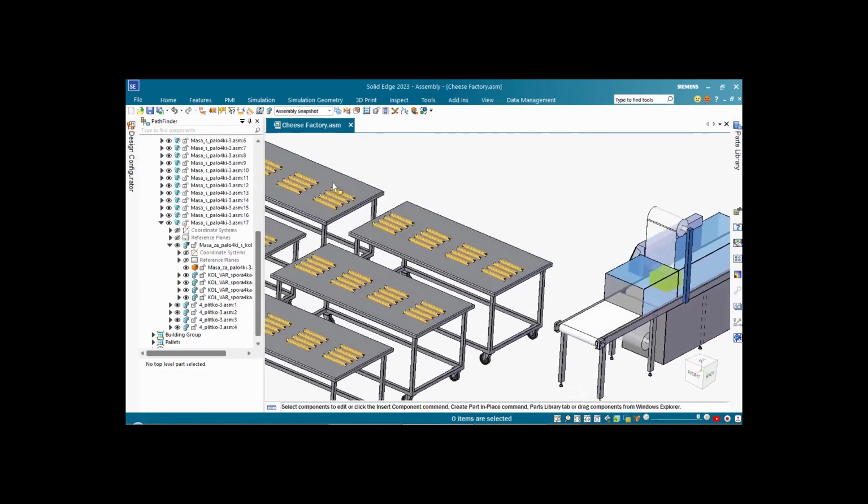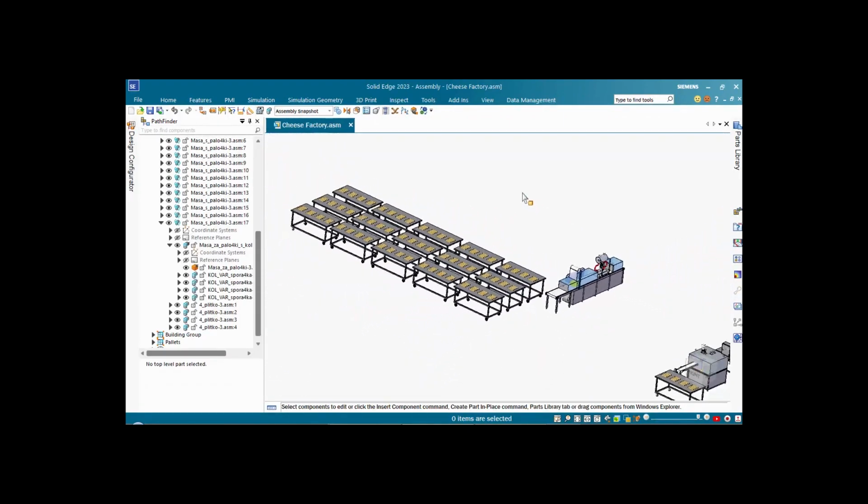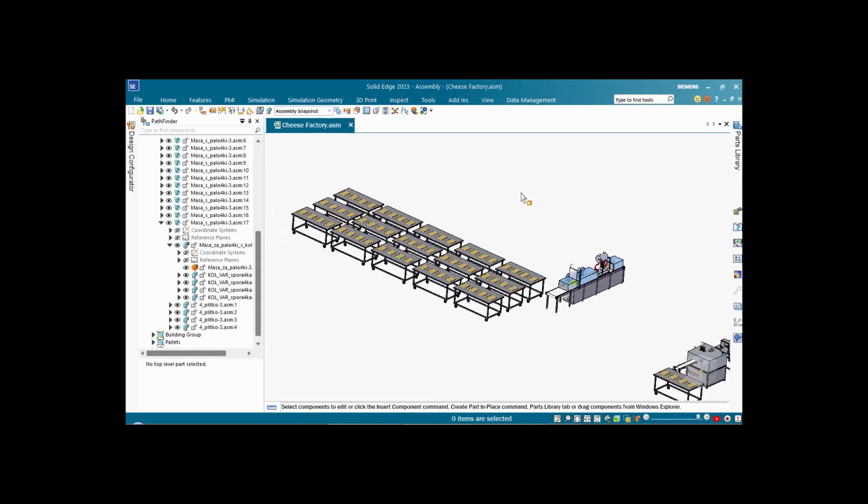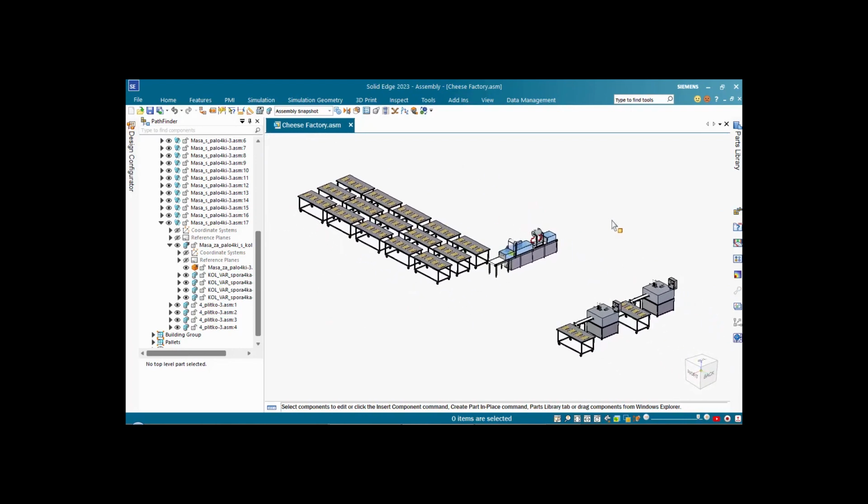And of course, if you want to change configuration, you'll pay the full price. You will have to wait till components load into memory. But this is a really quick way to get to a specific area and enable it for editing without waiting till the whole assembly opens.